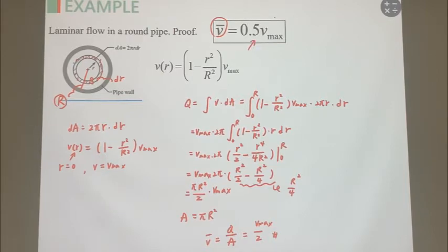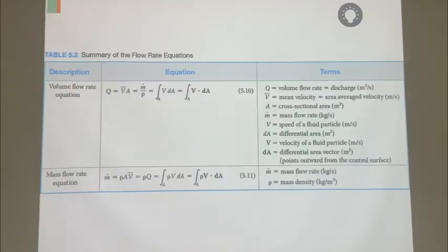Okay, so again, just keep in mind that flow velocity always follows this formula. If you consider your flow is pipe flow, then half of the V maxima is equal to the mean flow velocity.